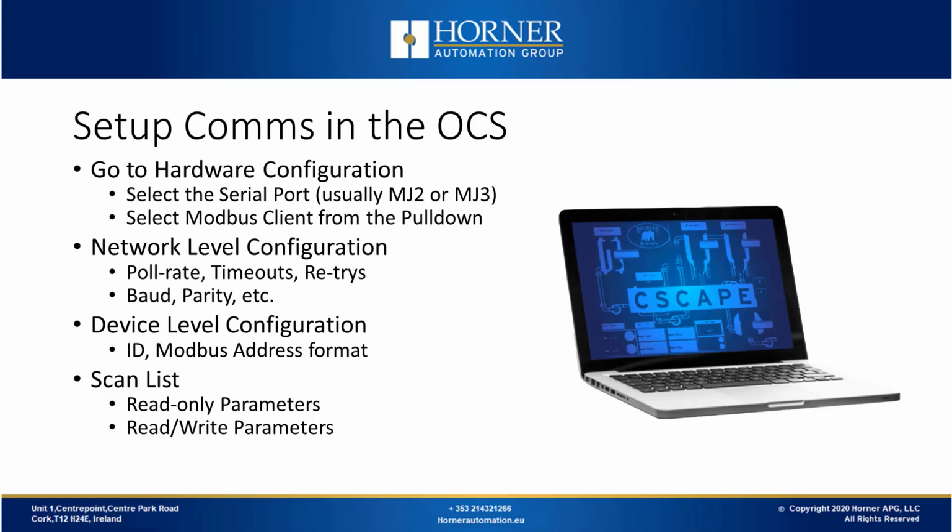Then we will do some configuration of the Modbus protocol on the OCS side. Firstly, at the network level, we'll be adjusting baud rates and timeouts, etc. We're going to have some device level configuration for each drive that the OCS is talking to. Then we're going to create what's called a scan list, which is real-time data that the OCS is going to monitor on a continuous basis out of the drive and place in local OCS variable space or register space so that you can access it anytime you want. If you ever want to change it and it's a writable parameter, those are the steps involved.